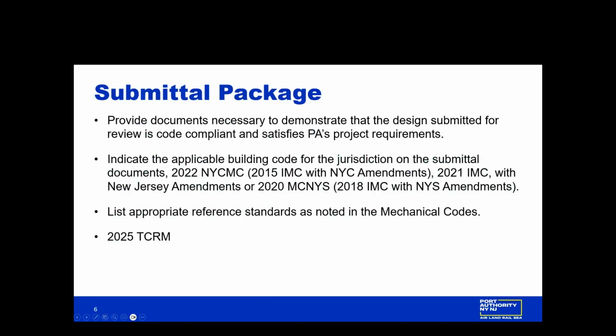So the submittal package, what does that consist of? When it comes into QAD, I like to have a nice complete package of documents to review. So you provide documents necessary to demonstrate that the design submitted for review is code compliant and satisfies Port Authority project requirements.